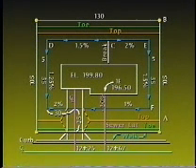1. Determine the ground elevations of the back of sidewalk at the following locations: driveway center line, southeasterly property corner, southwesterly property corner. 2. Provide the grade percentage between point C and the building pad. 3. What is the slope ratio from point A to the toe of slope? 4. Calculate the cut from the back of the sidewalk to the sewer lateral invert at the property line. And 5. Calculate the distance from the north property line to the toe of slope at point B.